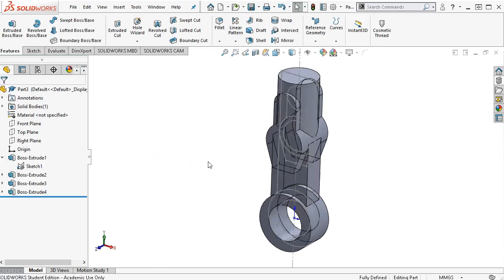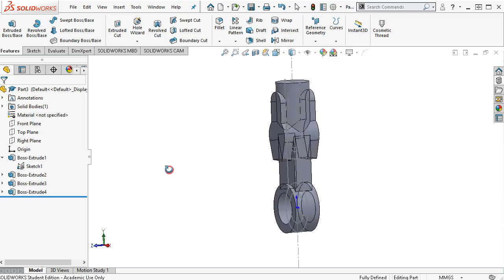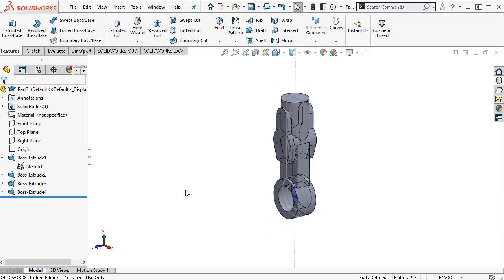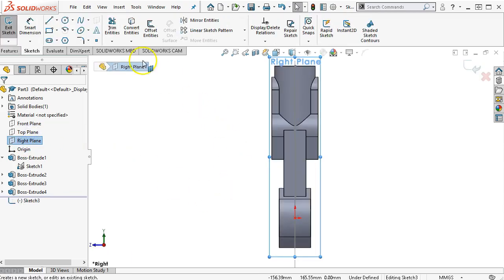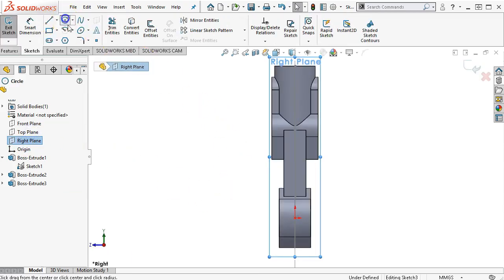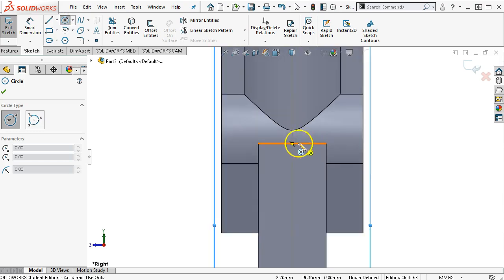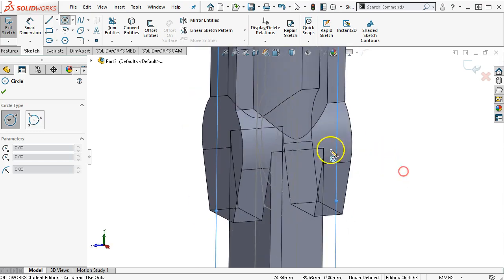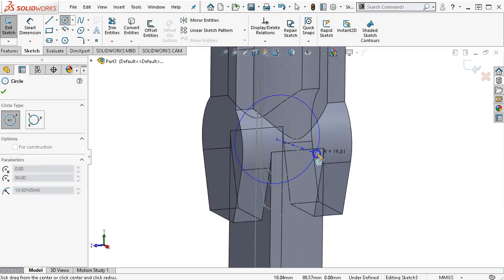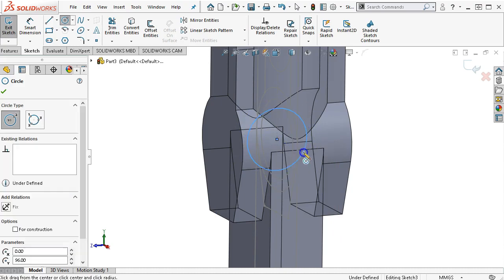All right, so a lot of geometry in there. Okay, I want to check for the side bosses then, so into the right plane and sketch. And still kind of keeping my eye out for that center point. Right, so we're inside. And let's see, it doesn't show me the backside, so the assumption is, it rotated over, radius of 0.25.